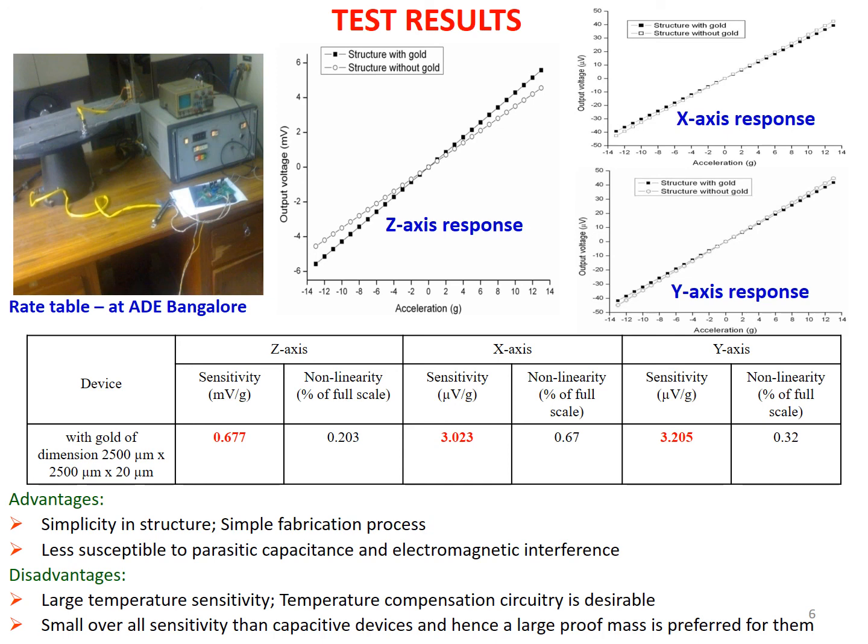This is just to give you the idea of the different features or parameters we have to look into when we design a particular sensor. After doing the design, before fabrication we have to do some simulation analysis, and there we have to see whether we are achieving our target or not. Once we are satisfied with our design, analysis and simulation, only then can we go for fabrication. Once the fabrication process is done, then we have to do the testing, the bonding and packaging, and after testing we have to satisfy ourselves that we are achieving our target parameter values or not, right?